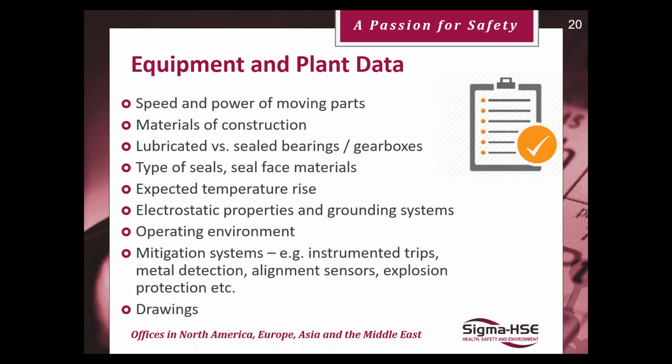And the operating environment is also quite important in that aspect. So maybe your equipment is run in short batches, so it might allow a degree of cooling. So it could be a potential safeguard when you have to fill in your tables. Yes, and the drawings are important. So just to know what the clearances are between, say, rotary equipment and the outer casing or the outer walls, and what mitigation systems you have. So, for example, you could have a reactor with a water-cooled jacket. It may provide a degree of cooling on the inside. So try to get as much information as you can when you're just about to start your NIRA.